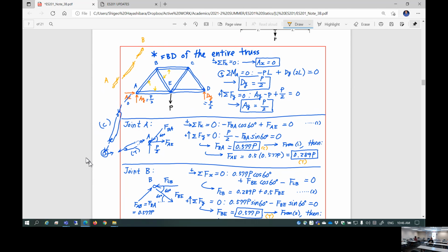Okay. If you say that yeah, the force pushes joint A. Force pushes joint A. Like the BA, that's AY. AY is actually pushing joint A up, but member AB is trying to resist it by producing compressive internal loading. But if it tries to resist it, it's supposed to be towards point A. Yeah, towards point A.